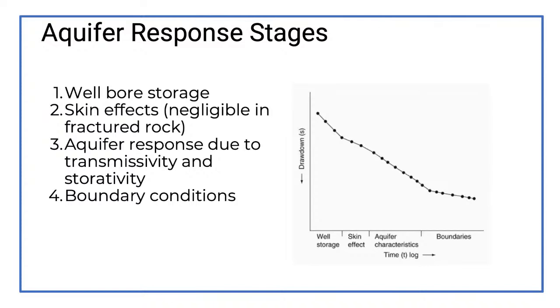You're going to have your storage in the well bore initially. That's the water that's in the well. Then you're going to have your skin effects that we're going to see, and that's going to be pumping the water out of the gravel pack and right around immediately surrounding the well. If you're in a fractured bedrock aquifer, that's not going to apply. Then we're going to start seeing aquifer response due to transmissivity and storage, where you're actually measuring the aquifer properties.